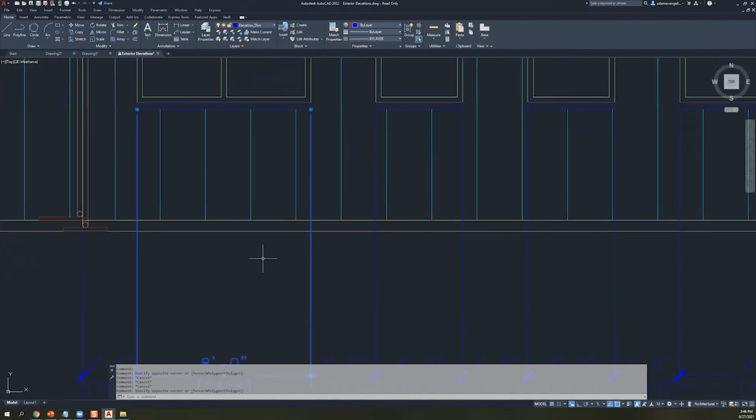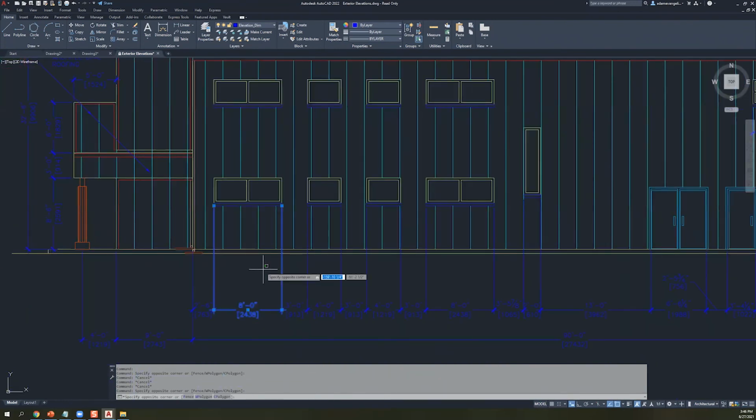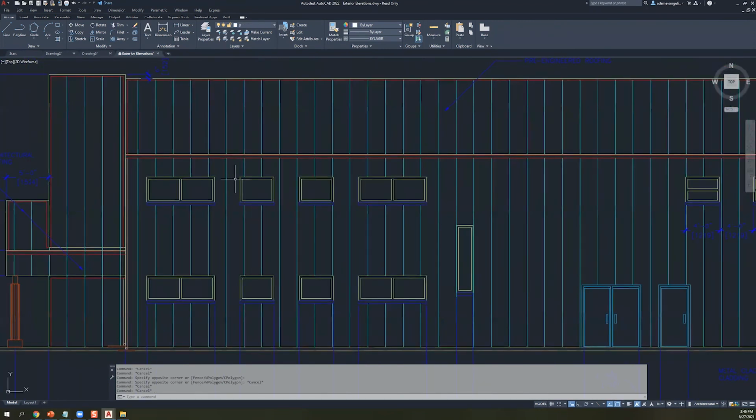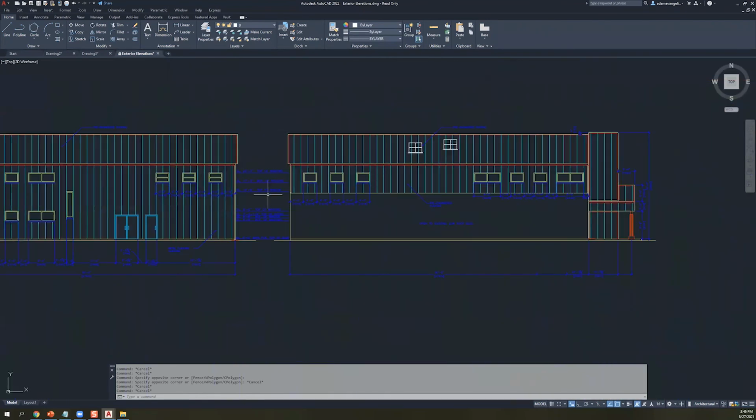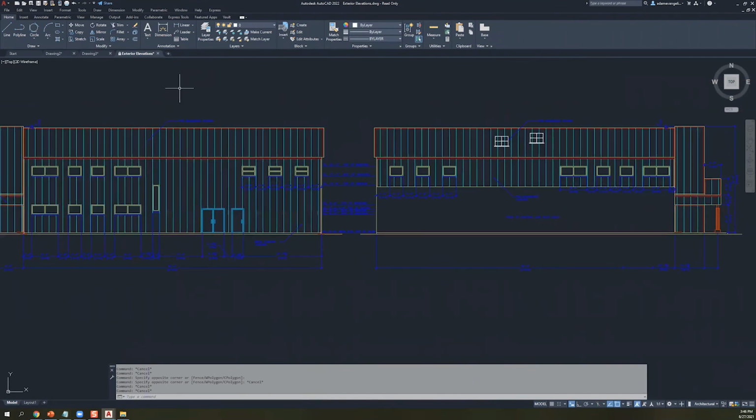I'll come back to styles and scaling in a little bit, but just bear in mind that you could place annotations on the model space, even if the model space is a one-to-one model, right? That's totally fine. Where things get kind of tricky, and where you might have to transition into the real world eventually, is when you actually get to printed drawings, right? Printed drawings could refer to physical drawings, of course, but they probably more often now refer to PDF and digital drawings in particular, right? So this is great. You might want to polish it up some more when you publish it to an actual published format though, right? And so that's where paper space comes in.